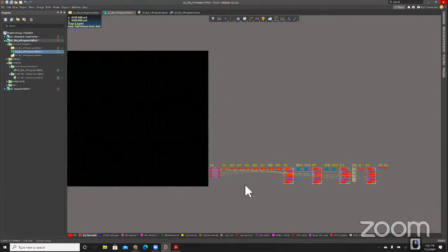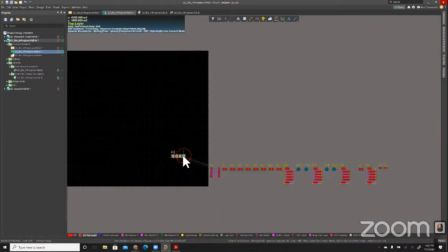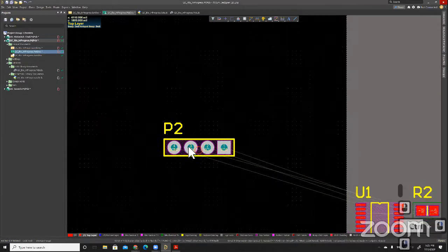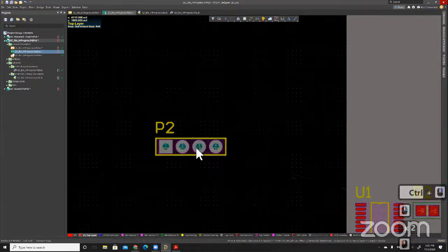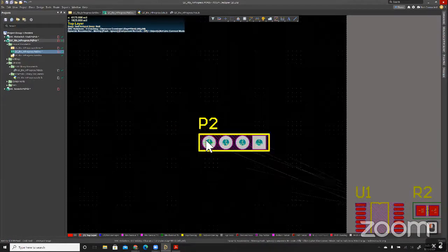So the first thing that you'll want to do is just start placing your parts where you think you want them to be relative to everything else. So the Robo Rio is obviously an immutable part of it. We want to make sure that that matches. And what you'll want to do with this part of it is go look and see, is the D ground on the right-hand side or is the D ground on the left-hand side?